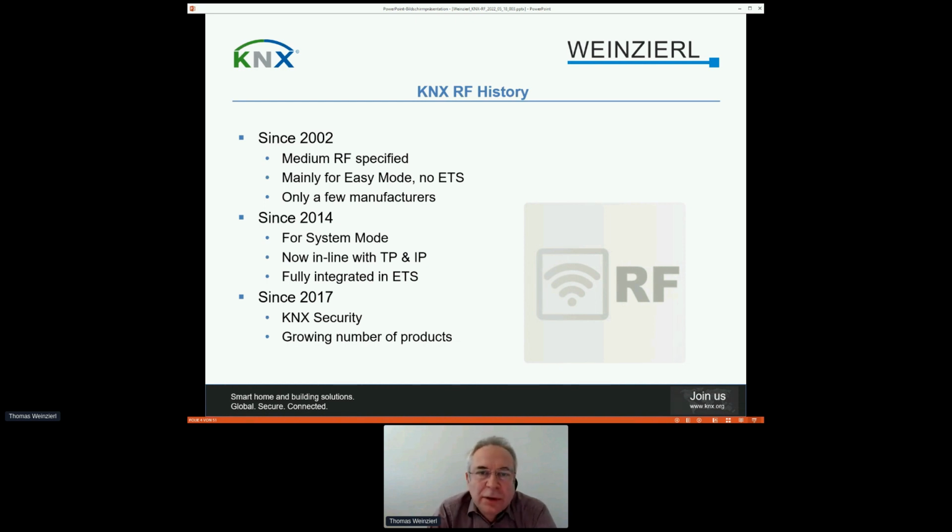So you have a smooth integration of wireless technology and also in a wired Knx network. And since 2014, this new flavor of Knx Rf is fully integrated into ETS. This was done in the context of ETS 5, but of course now it's also fully available in ETS 6.